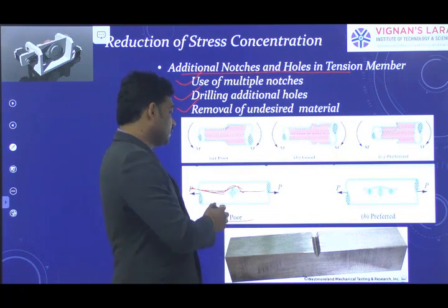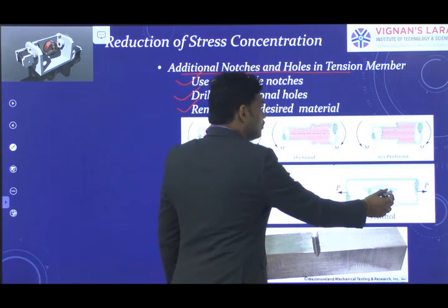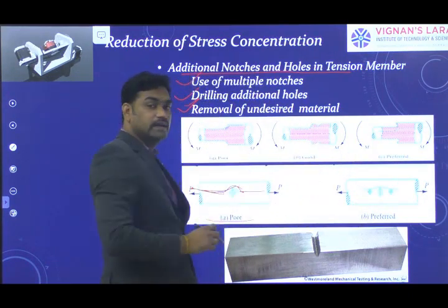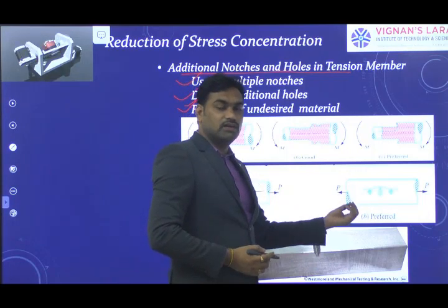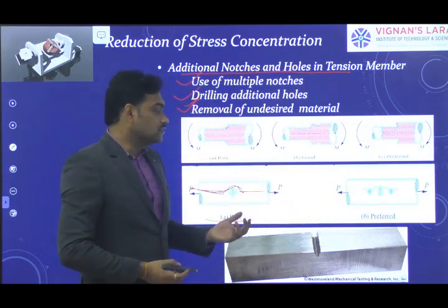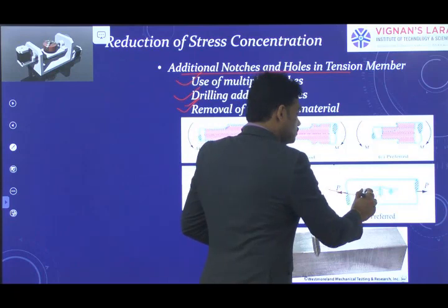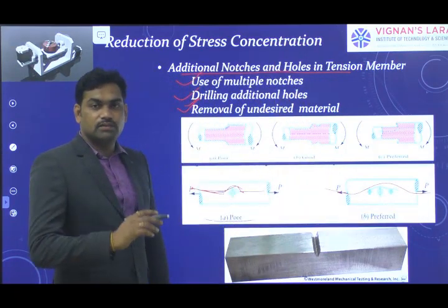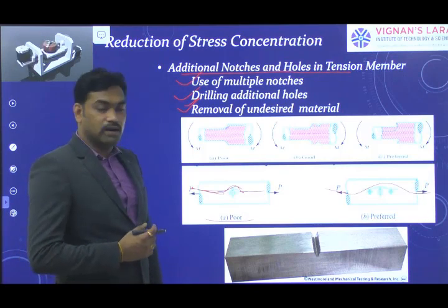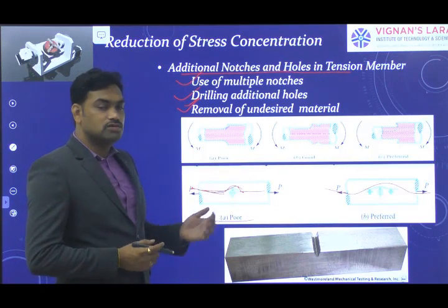So you can drill additional holes. That is one of the methods here, drilling additional holes. If you drill the additional holes before and after the required hole, then these stress lines can pass smoothly over the required hole. That is the additional holes we are providing.